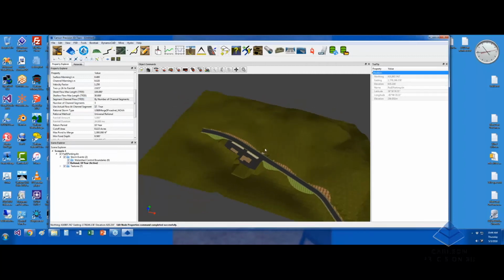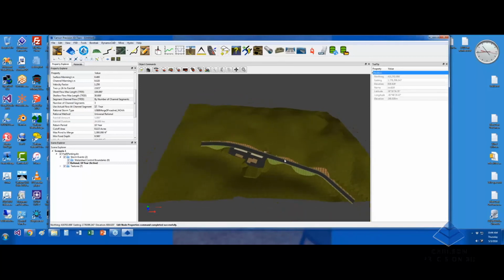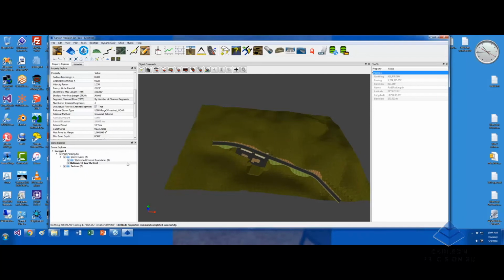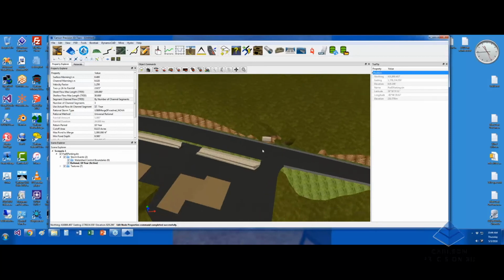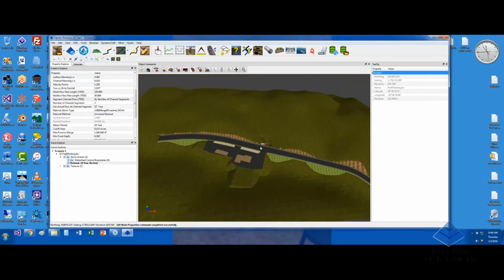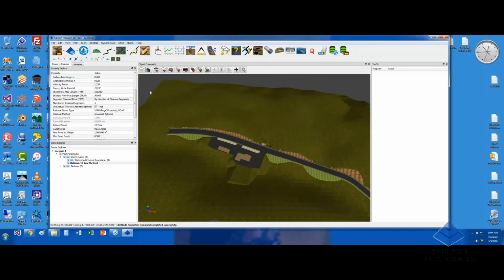So you can see I'm tracking, and my lat long is 38, 38, 38. I've already got all my textures mapped to the different runoff coefficients that I need. In this case, a lot of them default to 0.65 for rational, 65 for the SCS method. I'm just going to calculate the storm.